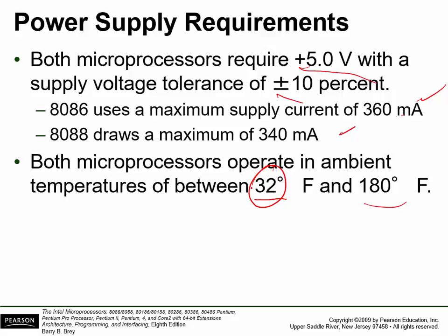Electronics on the outside of the aircraft may be at minus 50, 60 degrees Celsius, but if they're near the jet engines, they may be up to around 150, 170 degrees Celsius. So temperature ranges of electronics are an important factor.